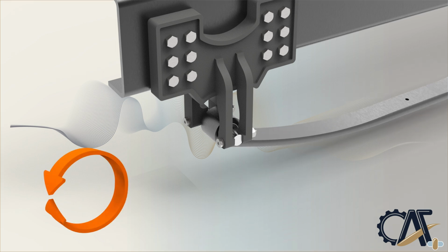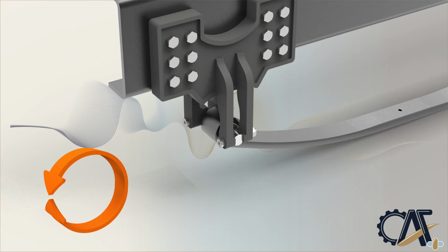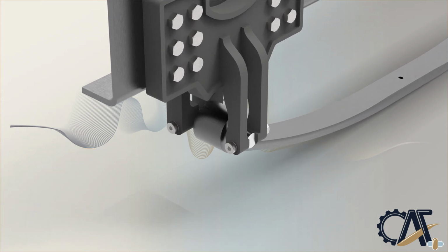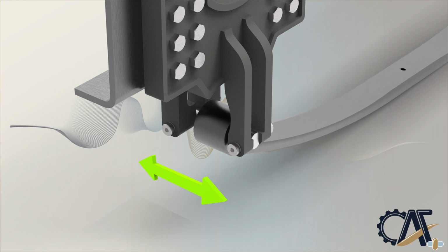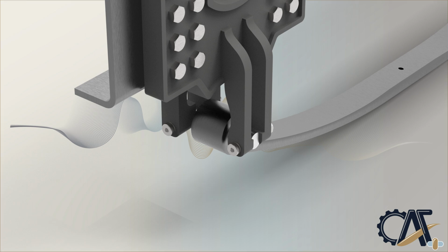In the first motion, the leaf spring is rotating along the axis of the bushing. This was shown in the motions of the bushing as the torsional deformation mode. In the next leaf spring motion demonstration, it can be seen the leaf spring is moving in the translational direction, or side to side. The axial deformation mode of the bushing will enable the leaf spring to have such motions. This motion on the suspension will happen due to lateral loads to the tire. We will be covering all the suspension loads in a separate video.